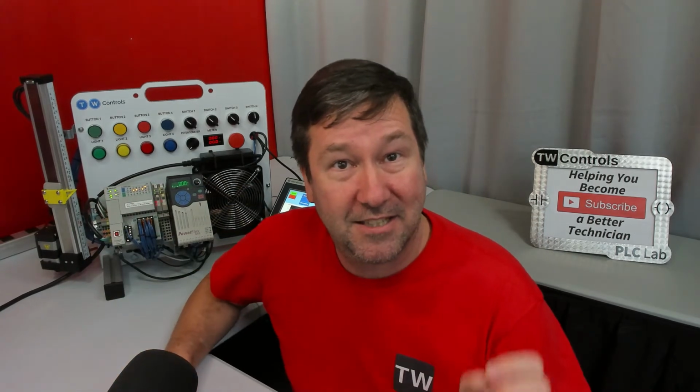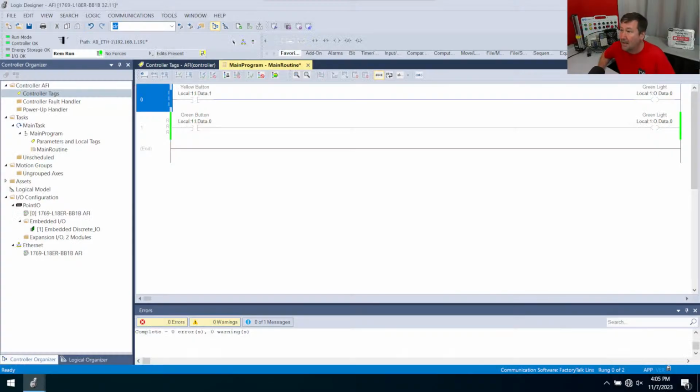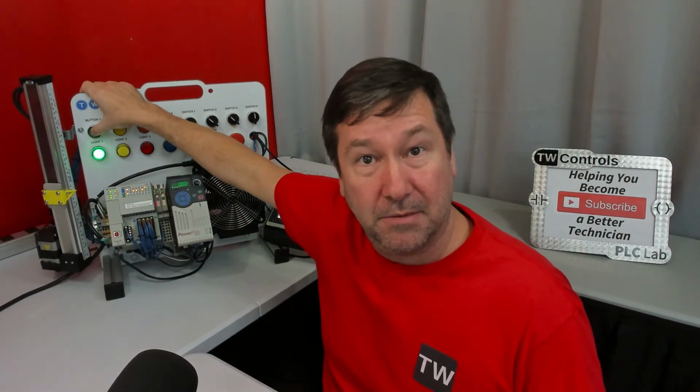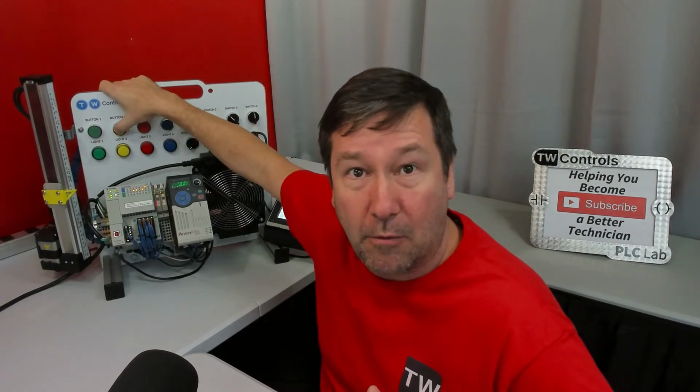And now we need to pay attention to the green on the screen to figure out what's going on. If we look here, right now, the one that has the R's, which is the old rung, is green. So that is the one that's running right now. And if I press the green button, the green light comes on, just like it did at the beginning of the video. The yellow light does not work.